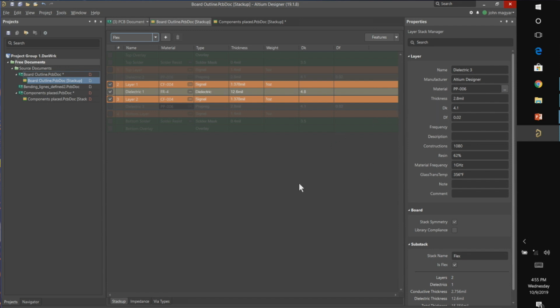Yeah. If you're doing rigid with flexible rigid, do you have a different stack up on each of these areas, or do you have to do the same stack? I believe the copper layer has to go through. So we used to have a different representation of this where it showed them all side by side. And generally the copper runs through.